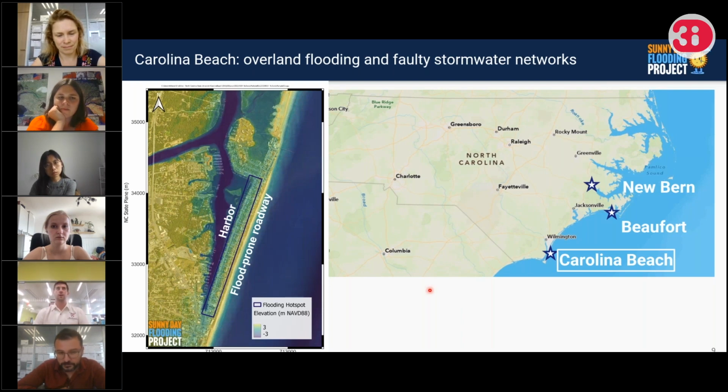So I think your question was about simulating waves in ADCIRC, and it's a very good question. The way that floods occur in Carolina Beach is that the flooding doesn't come from the open ocean here. The land is actually lower on the harbor side, so floodwaters move from the harbor, which is sheltered, to the roadway. And we've run ADCIRC and SWAN simulations, where we do include wave setup in our model, but when we compared the harbor side water levels from our ADCIRC simulation and our ADCIRC and SWAN simulation, we found basically no difference.